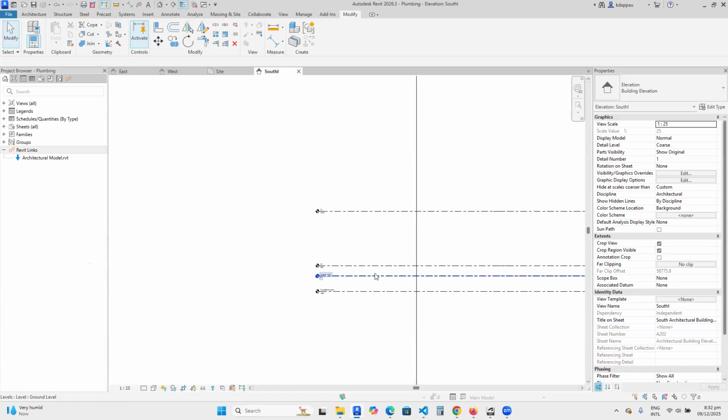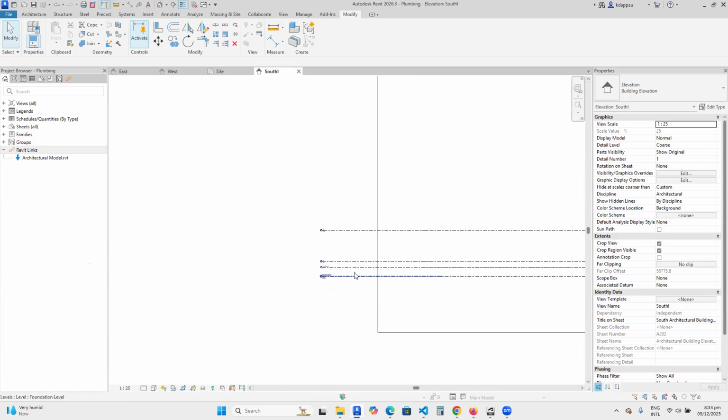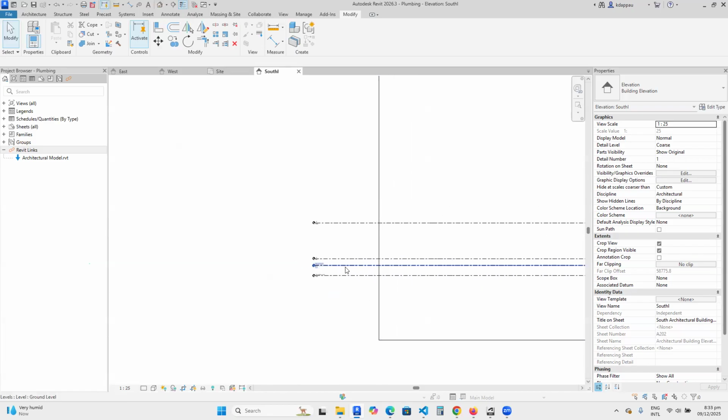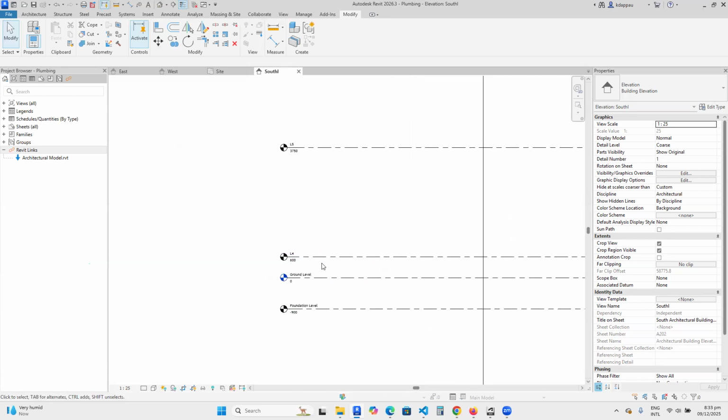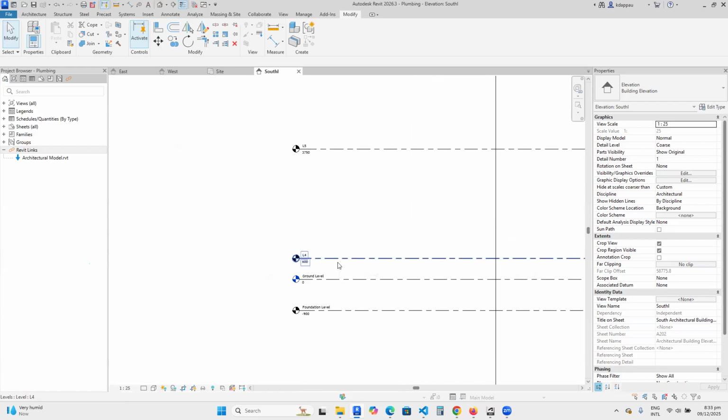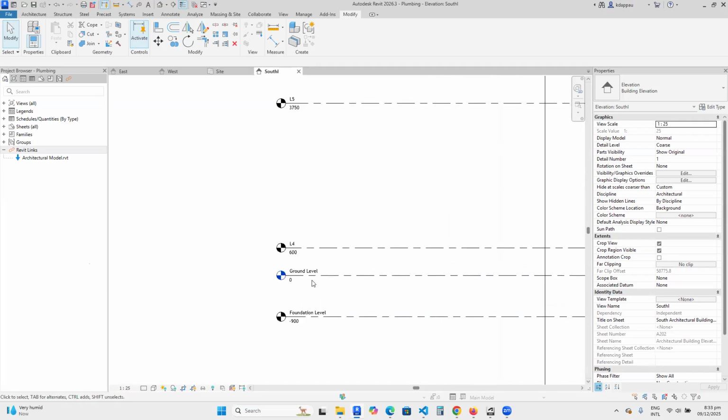Revit is not designed for a specific discipline. It's a multidiscipline, total building solution. So I want you to note that when you are working, each discipline has its own file. You don't model MEP in the electrical file. You don't model site in a building file. You don't model structures in an architecture file. You take your time and separate them as much as you can.